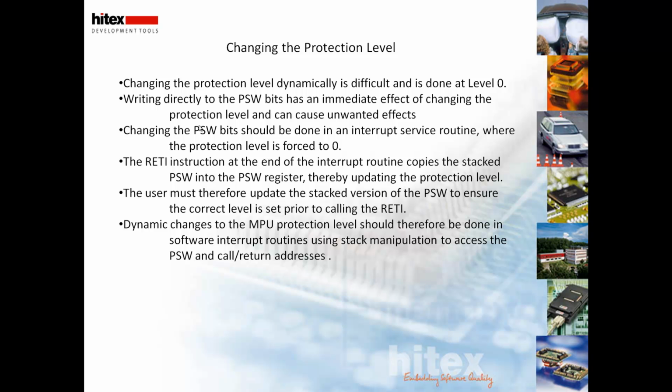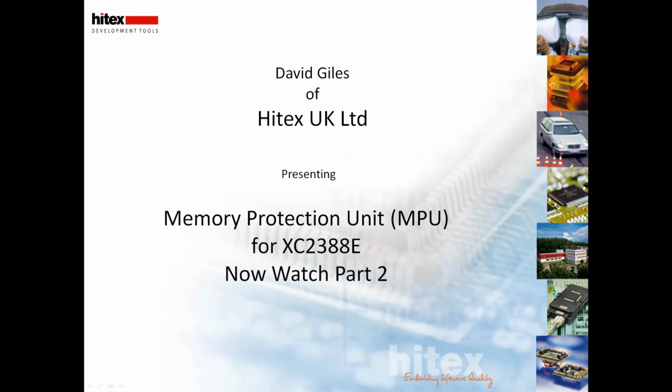The ret-i instruction at the end of an interrupt routine copies the stacked PSW into the PSW register, thereby updating the protection level. The user must therefore update the stacked version of the program status word to ensure the correct level is set prior to calling a ret-i. Dynamic changes to the MPU protection level should therefore be done in a software interrupt routine using stack manipulation to access the PSW and the call return address.